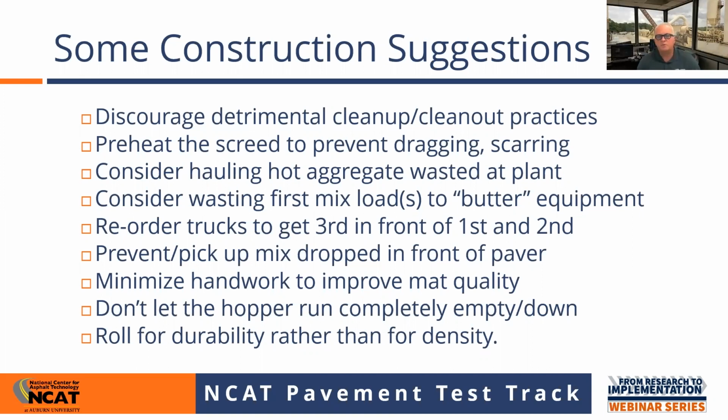All you want to do, if this is a good, stable, healthy mix, is, the word I like to use is seat. You just want to seat it on the roadway. When you over compact it, you're going to crush rock, you're going to collapse the voids, and then that mix is going to be damaged. So we're spending a premium for a mix that's going to improve safety on the roadway.